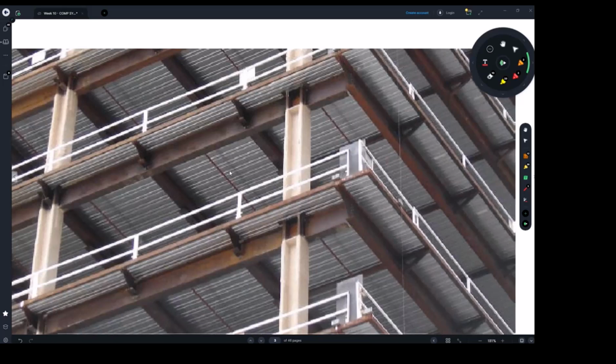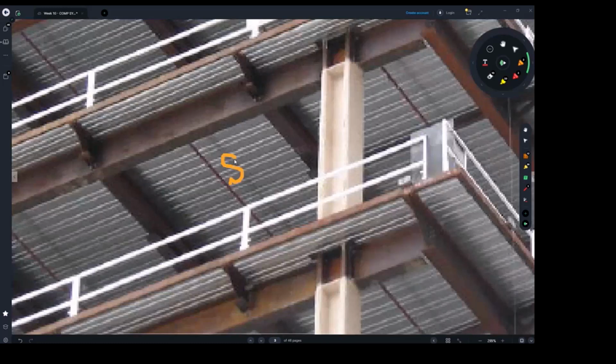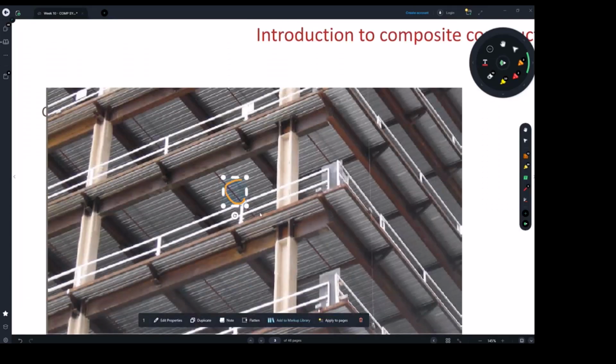So there are situations where people still think about using the bonding slab because they're going to be adding more reinforcement in the bottom, more than required, to help with fire. In case fire happens, the bonding is obviously going to lose integrity and lose its capacity. So the slab will be relying on the steel bars at the bottom to carry what it has to carry. So again, we will know more and more about this. I will let you use some span tables to make those decisions.